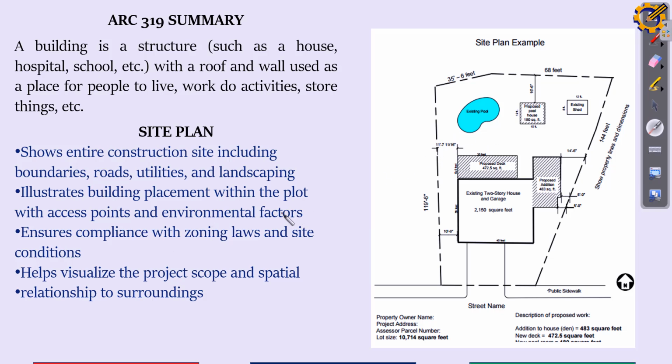So a site plan won't just show your piece of land. Let us assume you're building on something like 300 square meters. The site plan is going to show up to maybe a kilometer coverage, an area view of where your building is going to be situated. So it will show existing structures, existing public infrastructure, and the likes. It's going to show everything, the road network, everything leading to your building site. So that is what a site plan actually does.